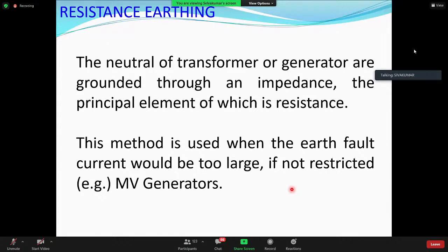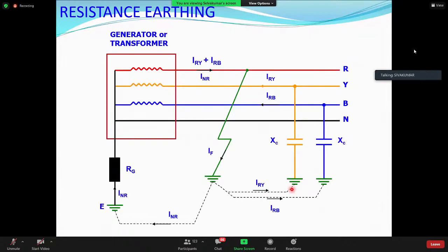Now, any industry has 70 to 80% of its electrical equipment as motors, rotating electrical machines. Assume the motor's body is solidly connected to the nearest earth grid or earth electrode. Now, inside, the winding is inside the core. There is an insulation failure in the winding and an earth fault happens, and the earth fault current goes to the earth through the earth grid.